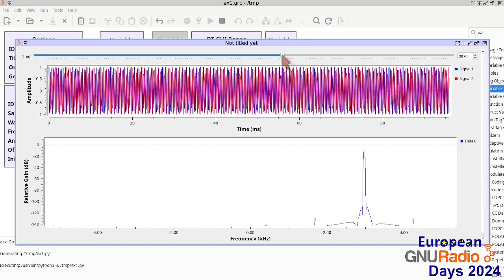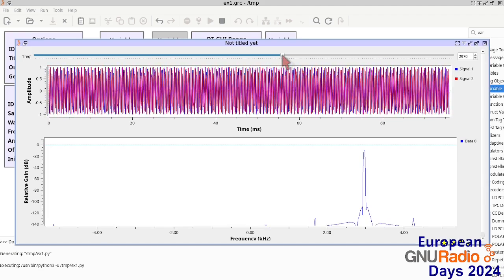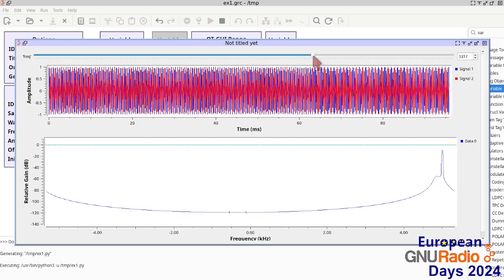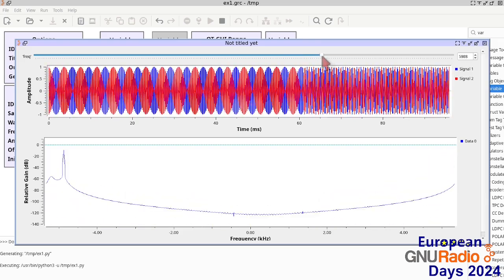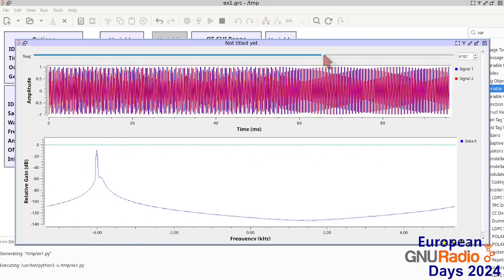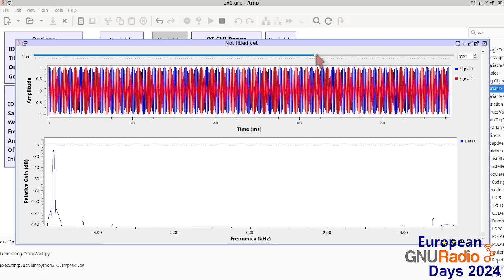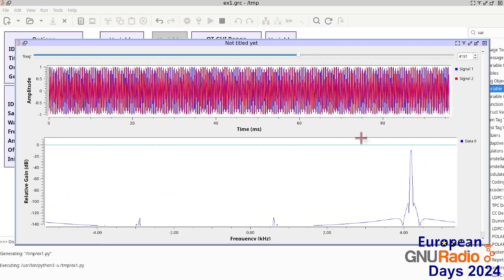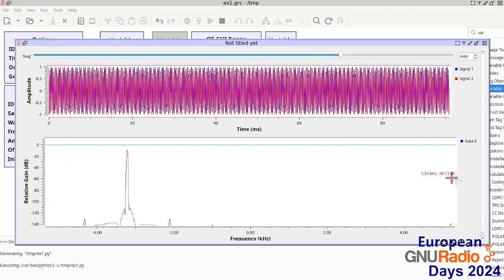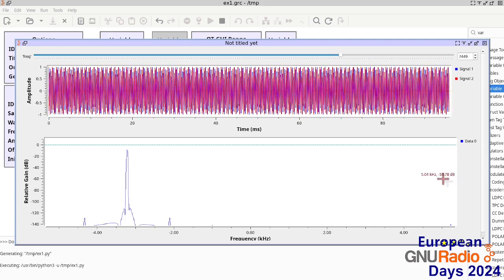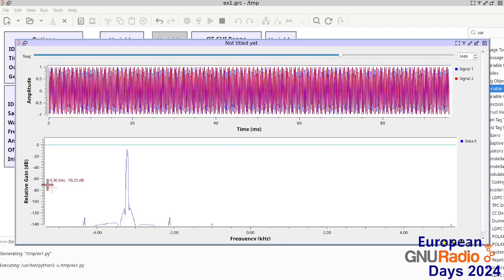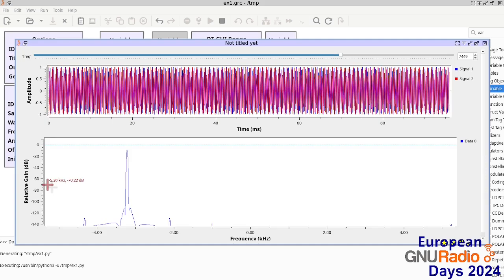When you have a discrete time Fourier transform, usually people say that the spectrum is periodic. Why do we say spectra are periodic? Because actually when you reach the Nyquist frequency, you see that it's not bouncing back, but it's coming back into the negative frequency range. So when we have a spectral component reaching plus the Nyquist frequency, it comes back at minus the Nyquist frequency, and similarly like this. So this means that whatever is happening here on the right hand side of the spectrum will be reflected into the negative part of the spectrum over here, hence this definition of periodic spectra.